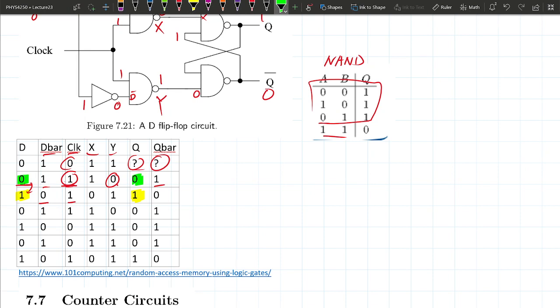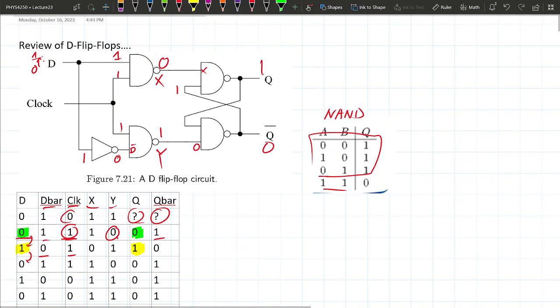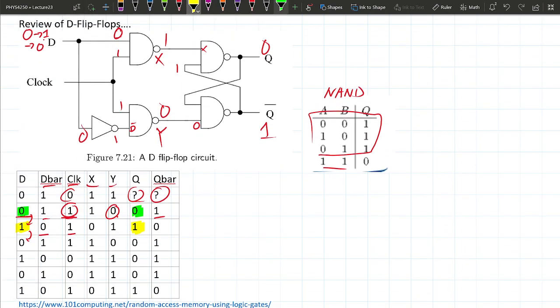And then if I flip this back down, the next row here, just to be a little bit long-winded, because I think I was in a rush last time. If I flip my 1 back to 0, let's go from here. So we started at 0, we switch it to 1, now we switch it back to 0. Now this input here is 0. The clock stays the same because we're leaving the clock alone at this point. This input here becomes 0, this becomes 1. All these kind of get flipped upside down, and hopefully now you see why they call these things flip-flops. They just flip every time you go through it, okay? So therefore, when your input goes from 0 to 1, your output goes from 0 to 1 also. The two just follow each other, okay?